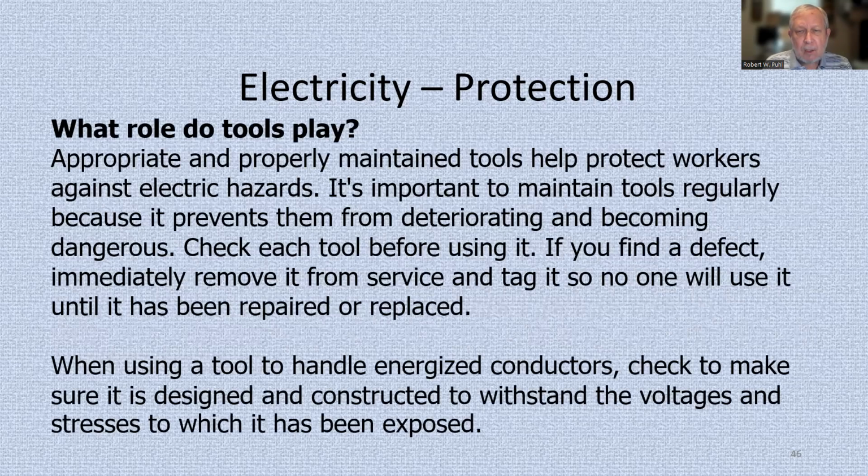What role do tools play? Appropriately and properly maintained tools help protect workers against electrical hazards. It's important to maintain tools regularly because it prevents them from deteriorating and becoming dangerous. Check each tool before using it. If you find a defect, immediately remove it from service and tag it so no one will use it until it has been repaired or replaced. When using a tool to handle energized conductors, check to make sure it is designed and constructed to withstand the voltages and stresses to which it will be exposed.